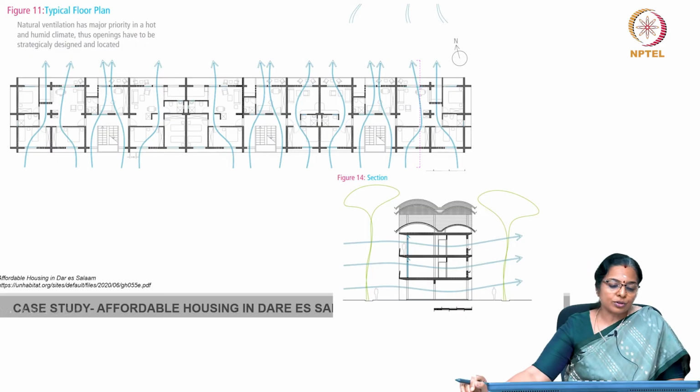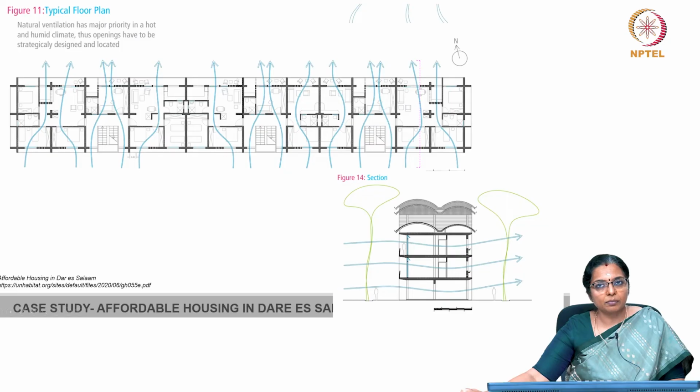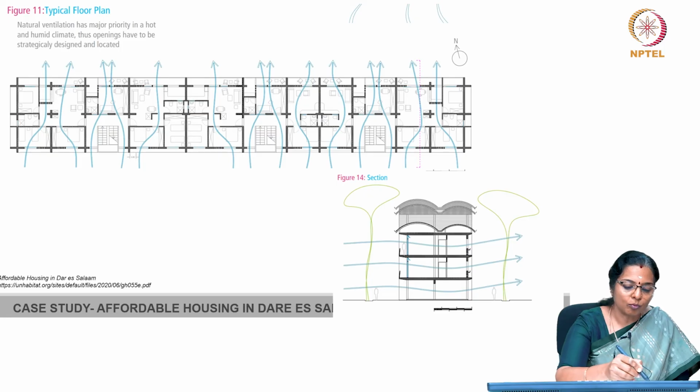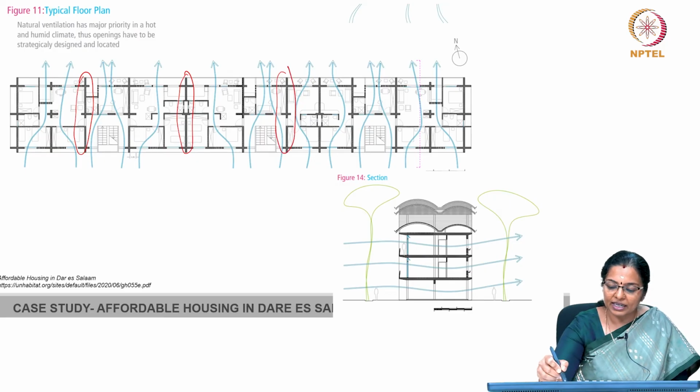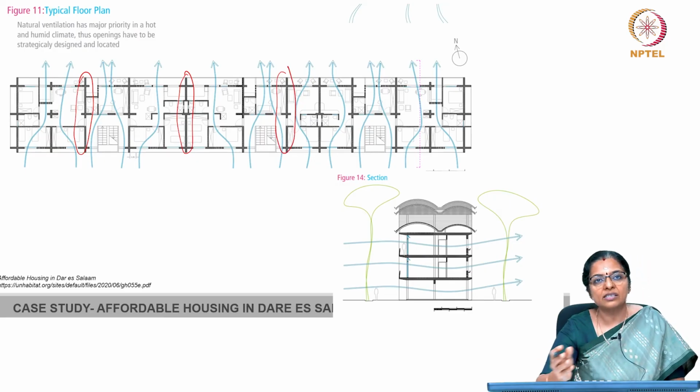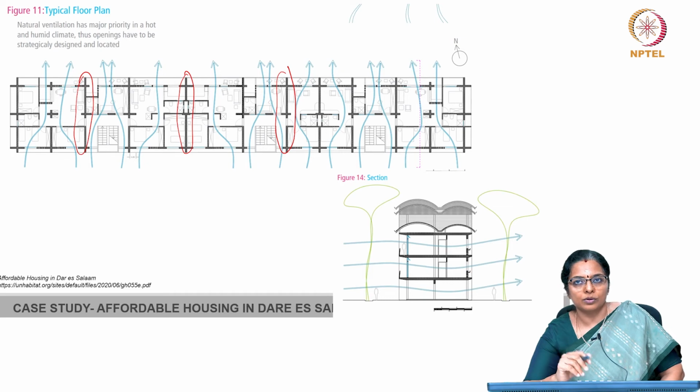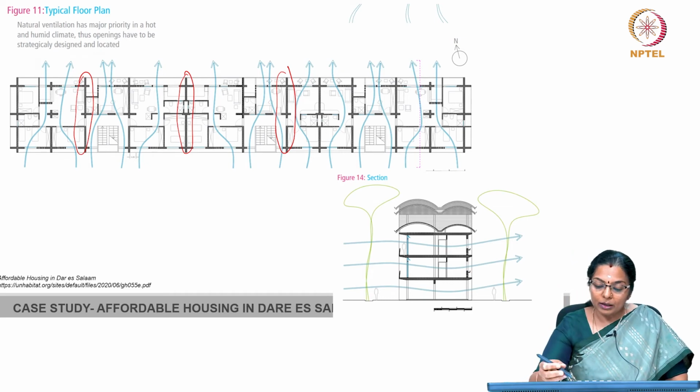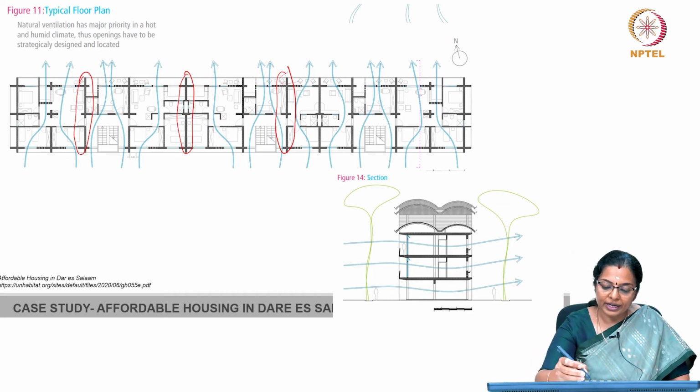So, most of the houses that you saw in the first picture, the primary facades of these apartment blocks are strategically oriented along the north and south. So, you can see for most of the houses, the western side is completely insulated. So, you do not get the western sun inside the house. Now, that is as far as orientation is concerned.